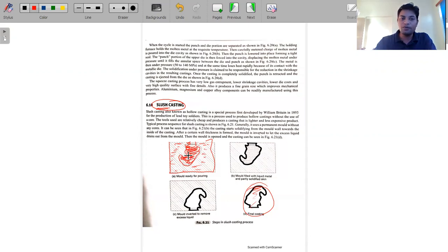Then we have the molten material, and we fill this molten material into that. When this molten material is completely filled, this black color is completely filled. Now there's a property of solidification, that solidification always starts from the boundaries. Boundaries means from this side.